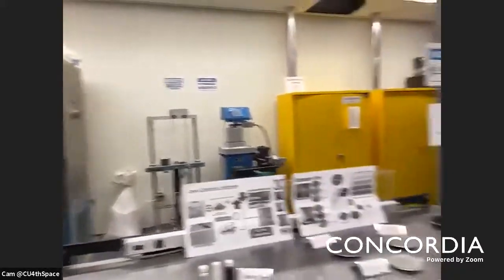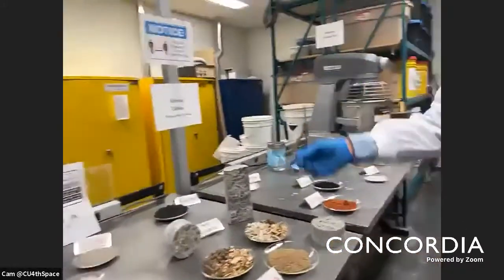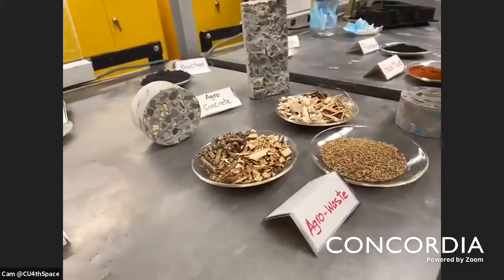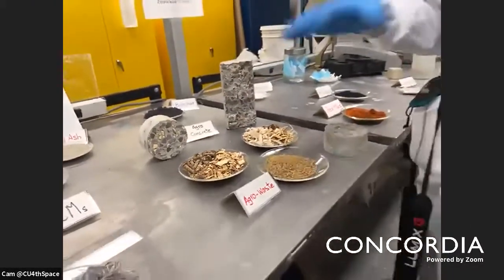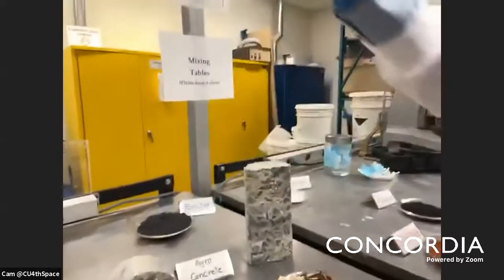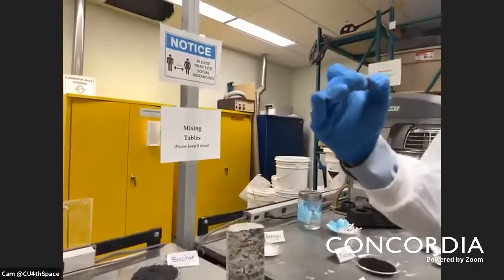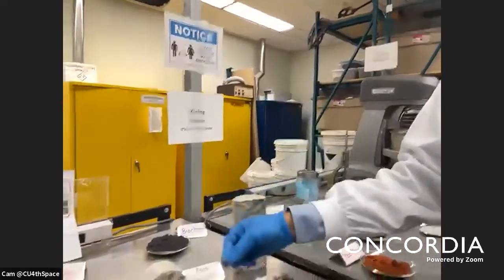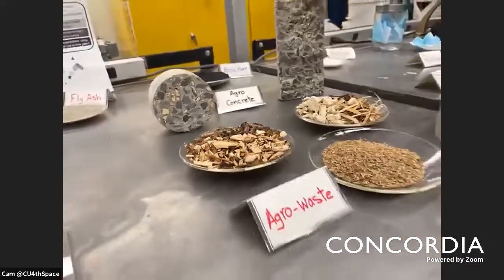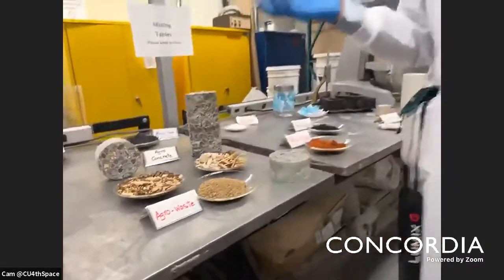Okay, some of them will work, some of them won't. And we can't say absolutely that all agricultural waste can be used. We have to make some tests. Some of them, for example, this one, when it absorbs water, it's going to expand and reduce the strength very significantly. Therefore, we try to use it in applications where we are not looking for strength, like control.